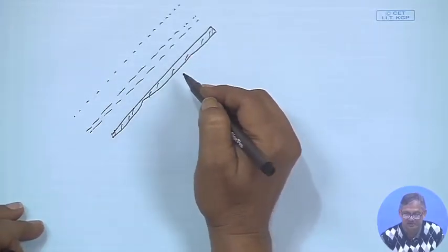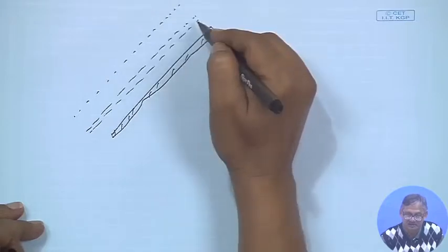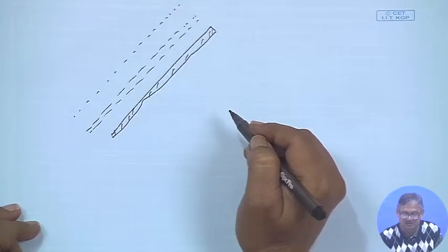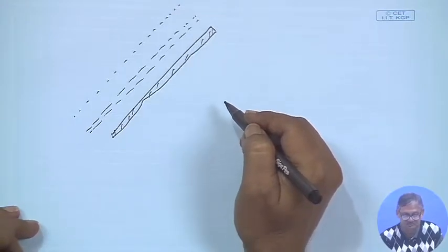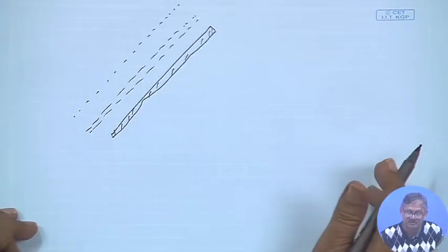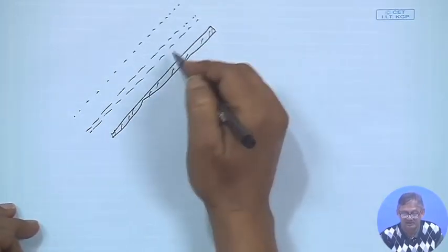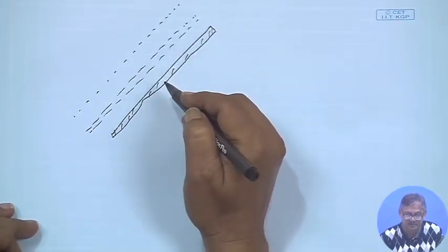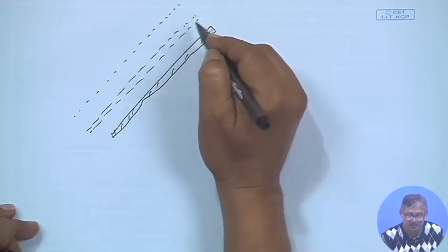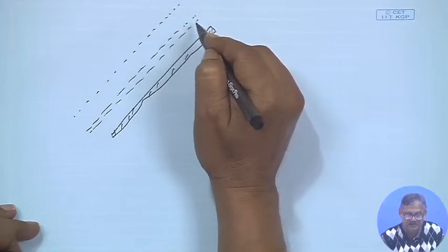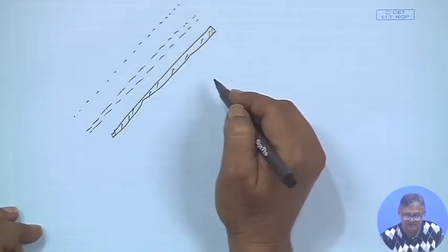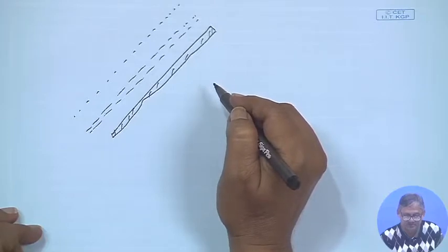If we look into an enlarged view, then if we take a volume element, here also we will do the mass balance or momentum balance, rather, that momentum balance on the volume element. This volume element, what we are looking into, that we have here say x, y and z, 3 coordinates if we are talking about, right.